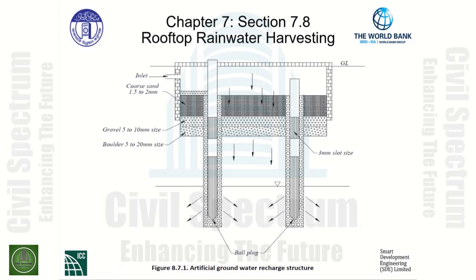Each rainwater seepage well shall have an inlet chamber with a silt trap to prevent any silt from finding its way into the subsoil water. The well should be terminated at least 5 meters above the natural static subsoil water at its highest level, so that the incoming flow passes through the natural ground condition and prevents contamination hazards. Again, no recharge structure or well shall be used for drawing water in any purpose.